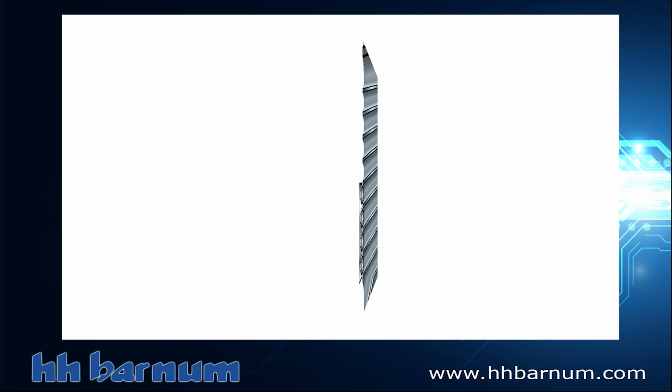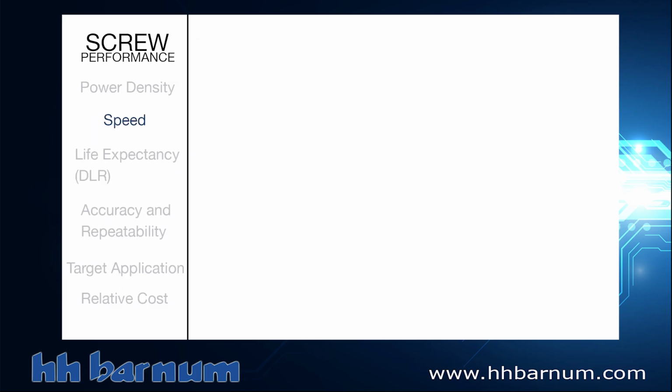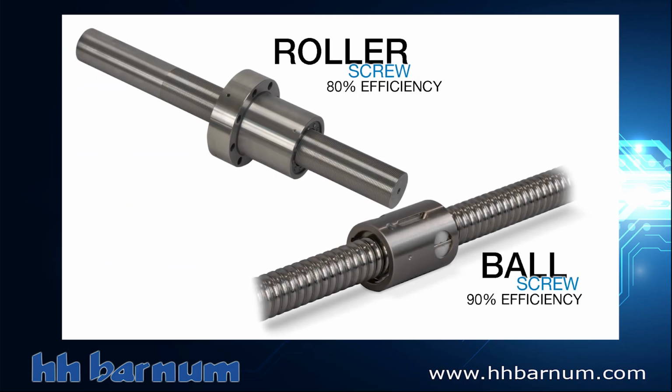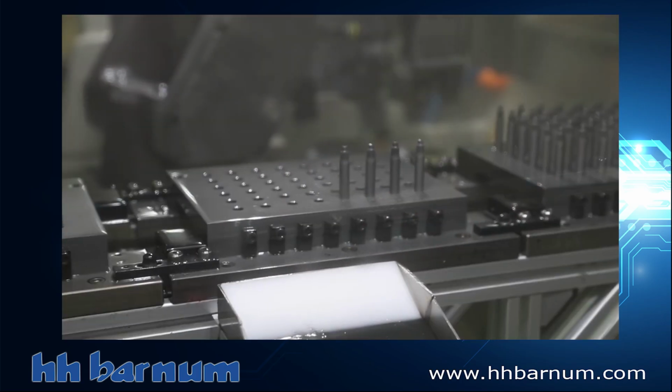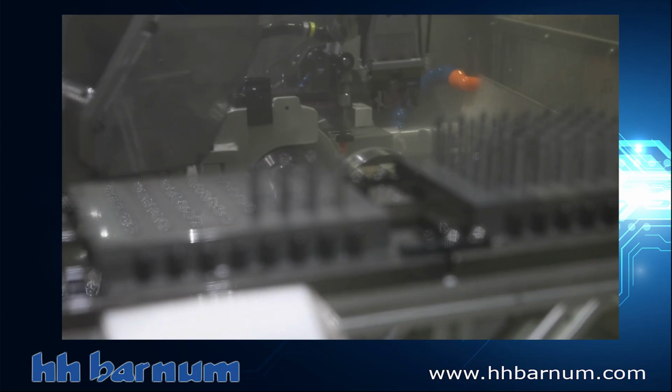By contrast, ball screws of similar size have lower contact surface area, which decreases force capability and life, but increases efficiency for high-speed applications. Roller screws have efficiencies in the 80% range. Ball screws have efficiencies in the 90% range. This is due to having fewer contact points, producing less friction, and resulting in less heat during movement.